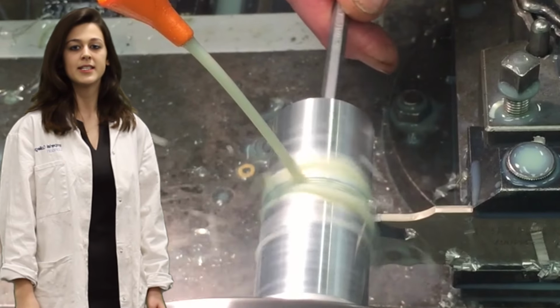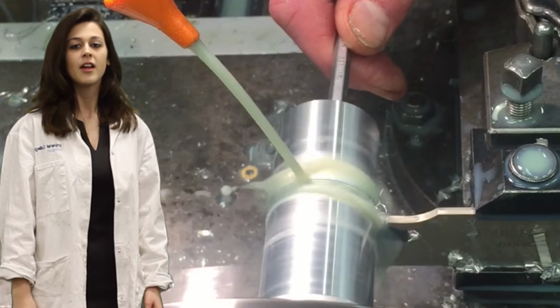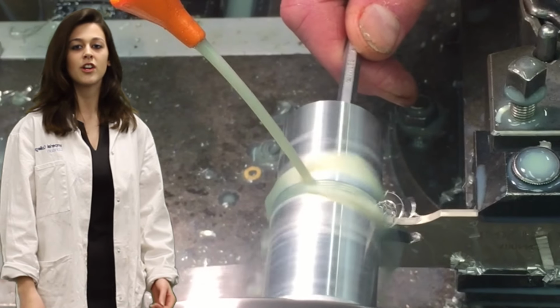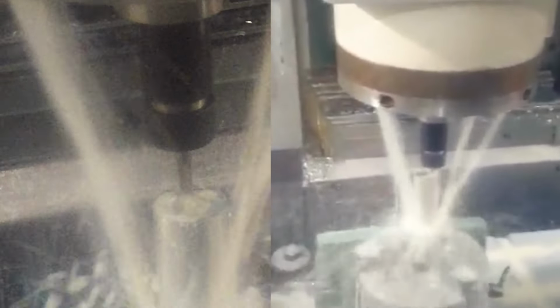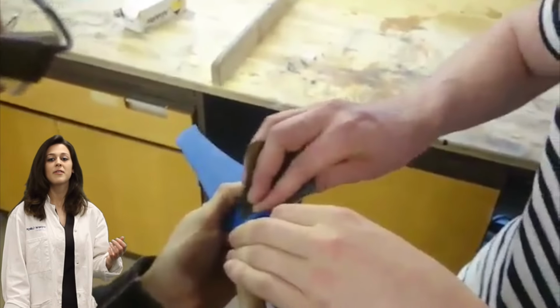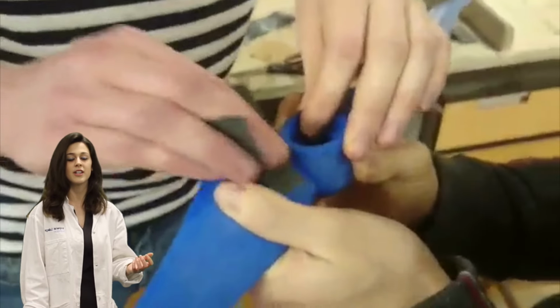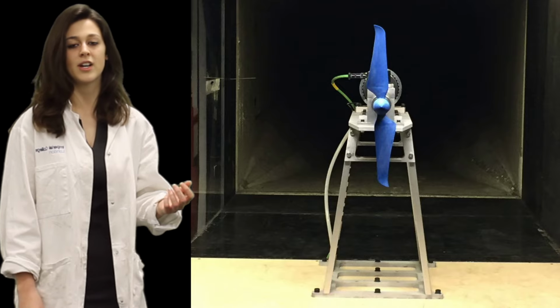Once the design was completed, manufacturing began. To make the hub, we started with a solid aluminium cylinder. We used a lathe to drill the hole in the hub on which the turbine would be mounted. A CNC milling machine was then used to cut the slots from the hub to increase the grip between the hub and cone. To refine the imperfections of 3D printing, the turbine was sanded to ensure a smooth finish and to remove the excess material that was added to ensure a smooth trailing edge.